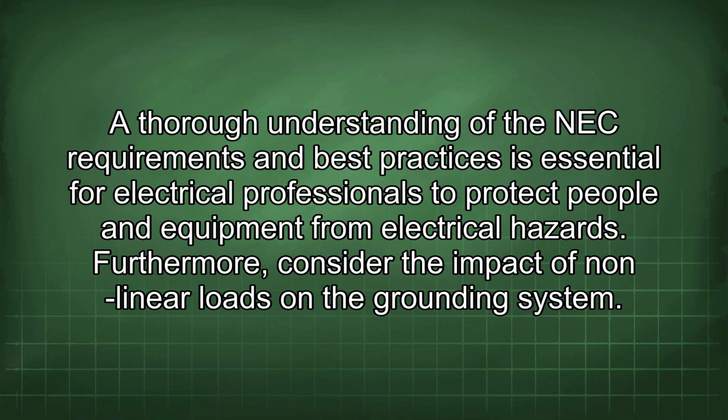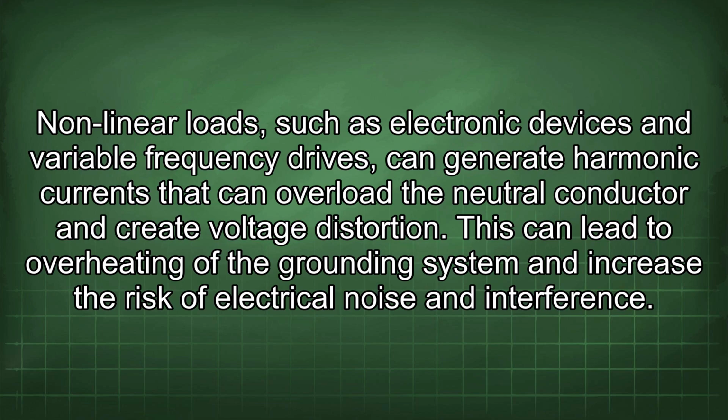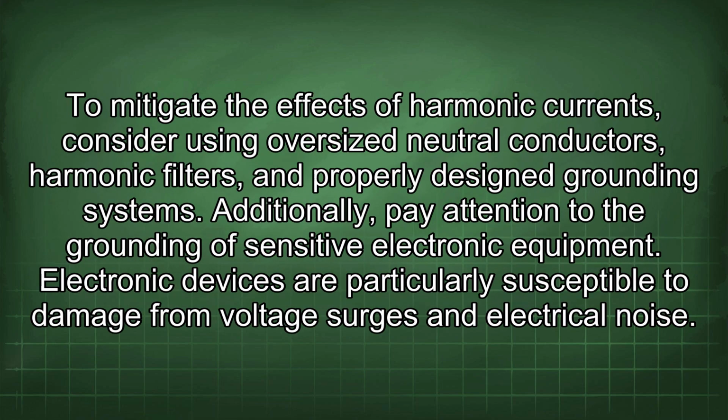from electrical hazards. Furthermore, consider the impact of nonlinear loads on the grounding system. Nonlinear loads such as electronic devices and variable frequency drives can generate harmonic currents that can overload the neutral conductor and create voltage distortion. This can lead to overheating of the grounding system and increase the risk of electrical noise and interference. To mitigate the effects of harmonic currents, consider using oversized neutral conductors, harmonic filters, and properly designed grounding systems.